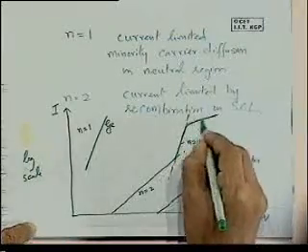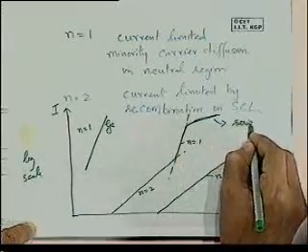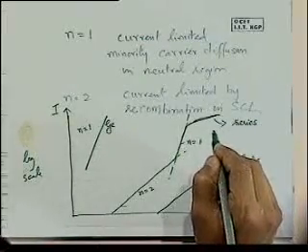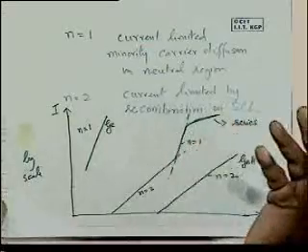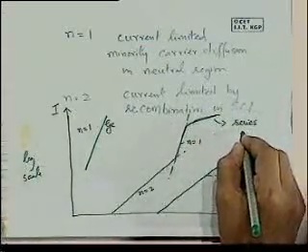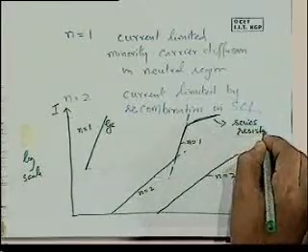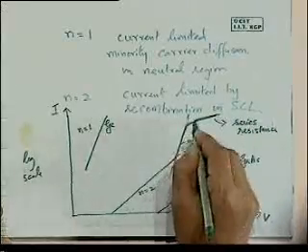What is this part here? Where we are beginning to see the series resistance, that is the resistance of the bulk of the semiconductor itself. Ultimately, in all these diodes, the current will be limited by the series resistance of the semiconductor. So if we took all of these curves high enough, we'll see them being limited by series resistance.